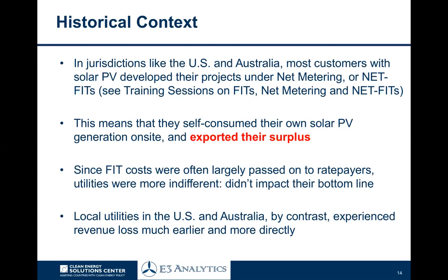This has important implications. Under FITs, for example, the customer continues to buy 100% of their supply from the utility, so the utility's cost base is not significantly impacted because they're not losing demand from self-consumption. The customer still buys 100% of their power from the utility. And the utility may then have to pay for that feed-in tariff generation to the customer, but under virtually all feed-in tariffs, they're also given the right to pass those costs on, or those costs are covered by government revenue, by essentially government subsidies. So under feed-in tariffs, it was more revenue neutral for the utility.